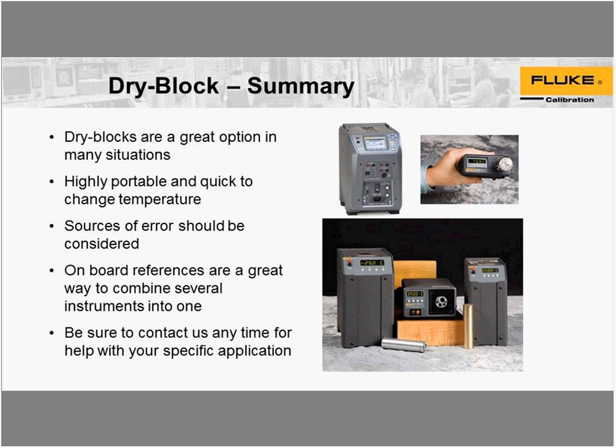All right, summary here. Drywells are a great option in many situations. They're very portable and very rapid to change in temperature. Again, just be wary of the potential sources of error that should be considered when performing a calibration using a drywell. Some of the ways to negate that are the onboard references or an external reference.